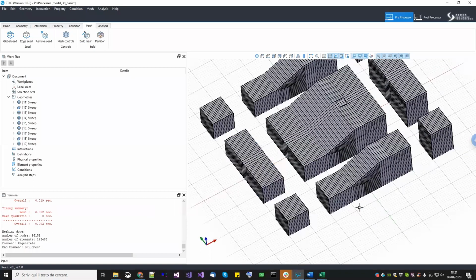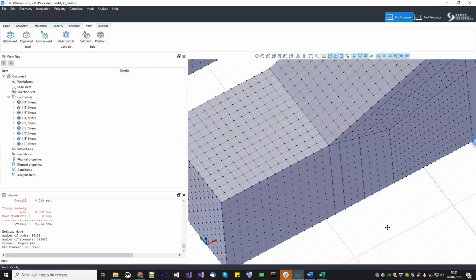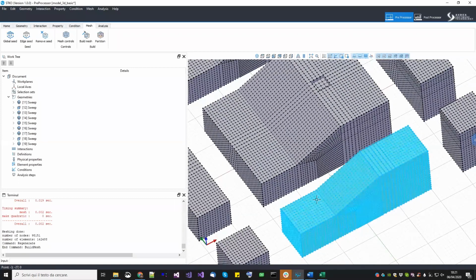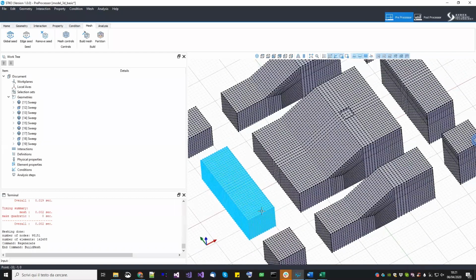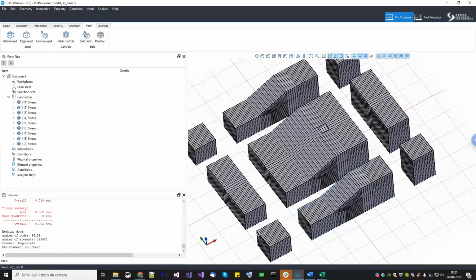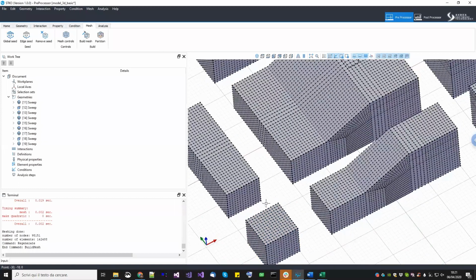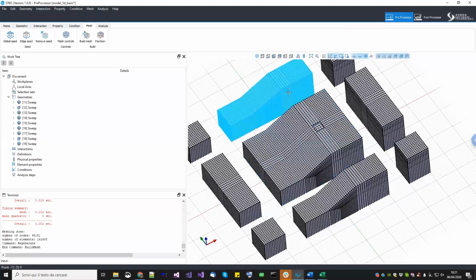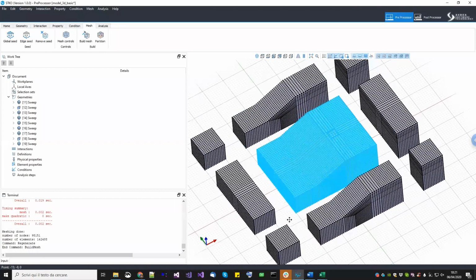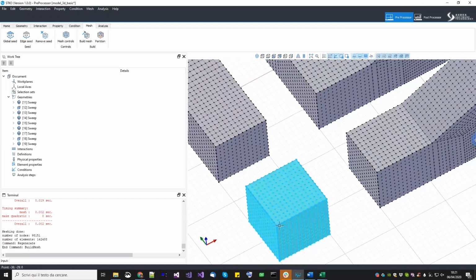As you can see, the mesh has been done, and everything is meshed as a structured hexahedron mesh. We need to do a small modification. As you know, all these boundary elements here are just free fields, so we don't need to do this discretization. For example, let's say this dimension is fine for the mesh as an overall size. But along these edges, for example, along this edge here, I just want one element because this one anyway is going to be a free field column, so I don't need the subdivision inside.